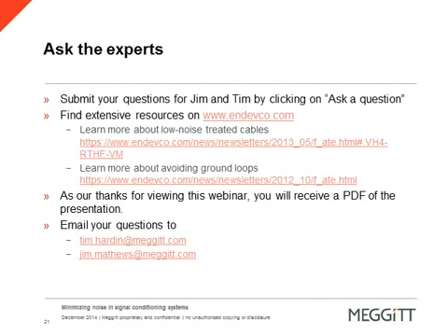So the high-frequency switching and so forth depends on where it's getting in. Is it getting into your cable run? Is it getting into the mount of the accelerometer? Then you look at your case design, which we talked about, and also the cabling. If you're using standard coax, you should be using low-noise treated cable, even if it's an IEPE type, just because of the type of situation you have.